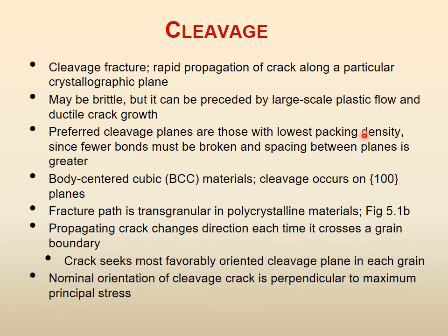Preferred cleavage planes are those with lowest packing density. If you go back to your material science, then you can find the packing density on each plane. Those planes where the packing density is low have less material to resist your loads, so those are planes on which deformation can happen more easily, right? Since fewer bonds must be broken and the spacing between the planes is greater, cleavage planes are those with lowest packing factor. In body-centered cubic materials, BCC materials, cleavage generally occurs on 100 planes, right?